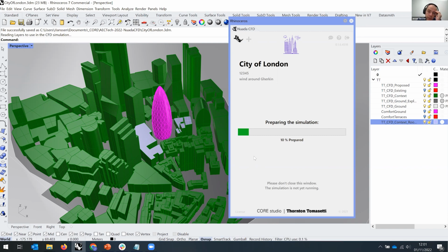The thing is that the ground surface typically is varying so much that I tend to not do it and just set that larger than the ground anyway, in a way. Because we're not extracting the beyond ground explicitly anyway, because we're not extracting comfort results for the ground. So you'll see that it actually often just stops already at the boundary. Yeah, it's a choice, I guess.